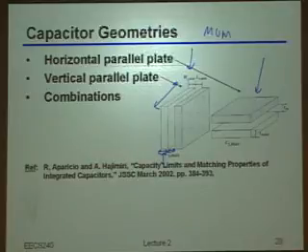The layer-to-layer thickness is probably going to be much more than the minimum spacing you can get horizontally between. Okay, so you said that this layer-to-layer thickness is probably going to be much larger than the spacing that you can get here. And I would tend to agree, but why? Well, the processes are mainly made for digital guys, and they want less interconnect cap. Yeah, right? Just to repeat for the camera, remember, the process is usually built for the digital guys, right?